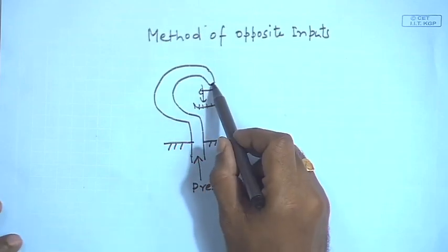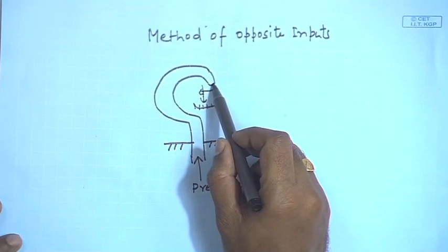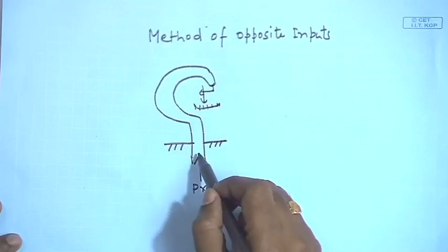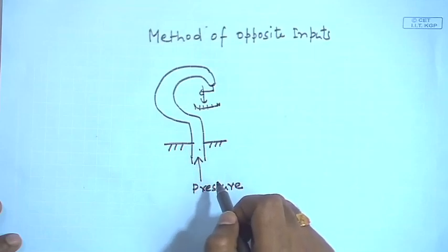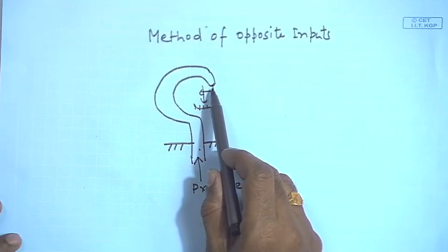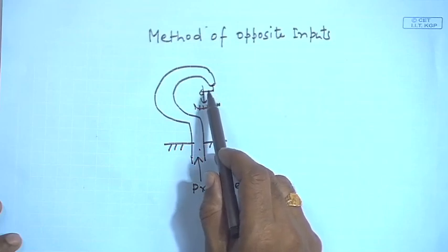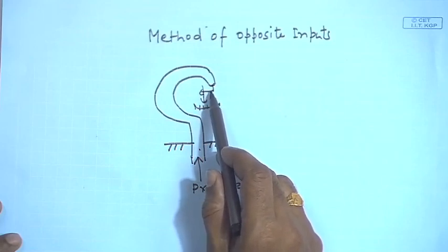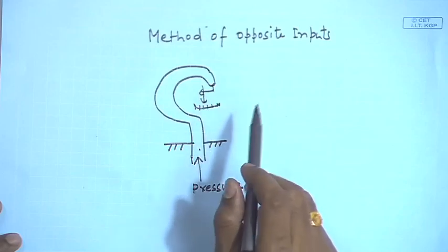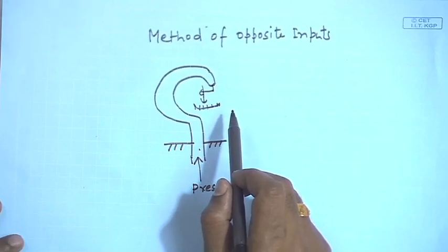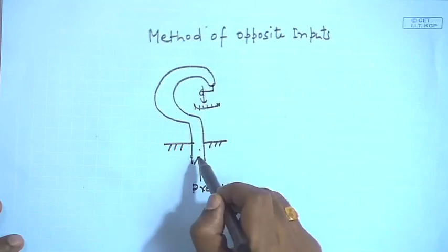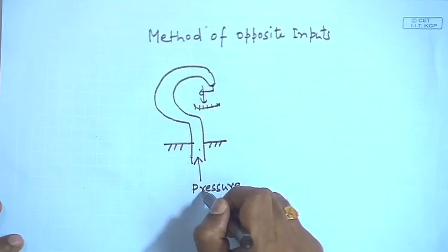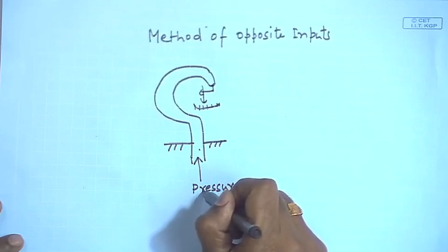We know that deflection of the tip is a measure of the pressure being applied inside the Bourdon tube. Now, the tip deflection depends on various factors, but for a given Bourdon tube, other things being unchanged, this tip deflection can be considered as a function of pressure alone.